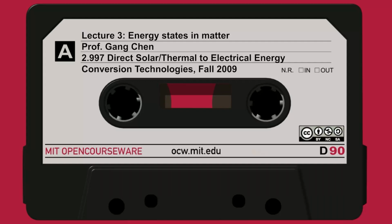And it turns out in silicon, the maximum point where the electron is filled to as a valence band, and the minimum point, that's the conduction band, they do not agree in terms of the wave vector. So this is an indirect semiconductor. And gallium arsenide, on the other hand, is a direct semiconductor.